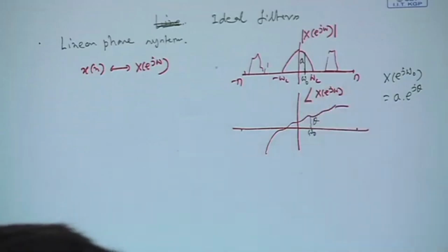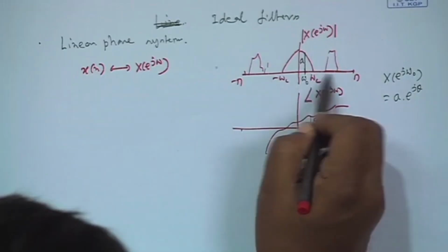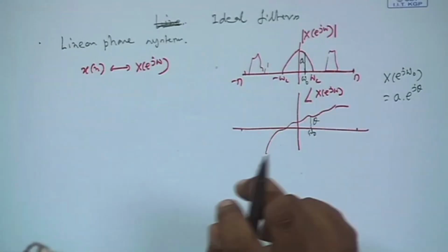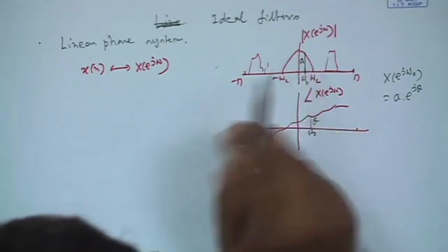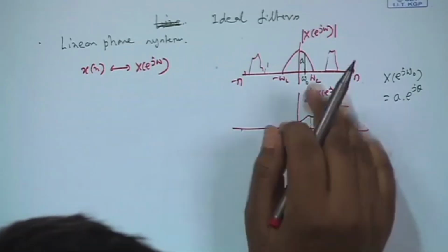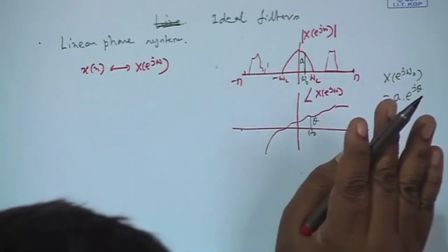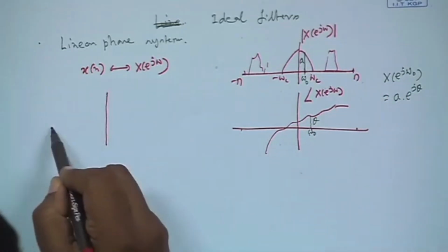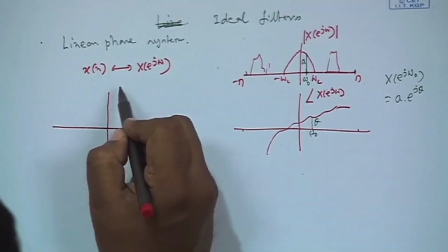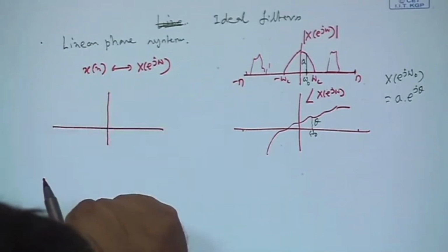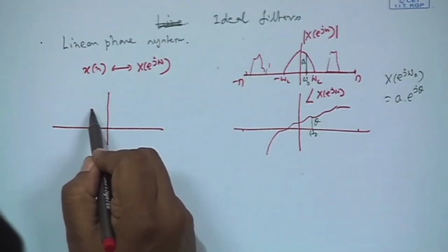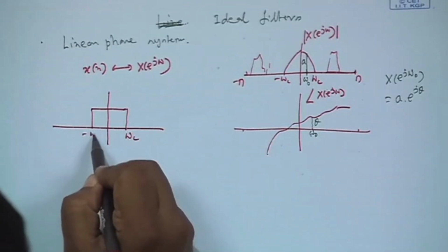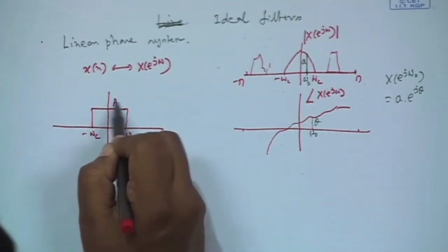So, suppose this is given to you, but nevertheless this is band limited within some band. Outside the band there may be unknown, unwanted components, noise and all. So, you have to filter it. Filter means you want to pass this signal as it is without any distortion and remove all components which are outside this band. Okay. So, then filter magnitude response, then what should be the filter? Firstly, from here to here, say omega c to minus omega c, its magnitude should be constant.